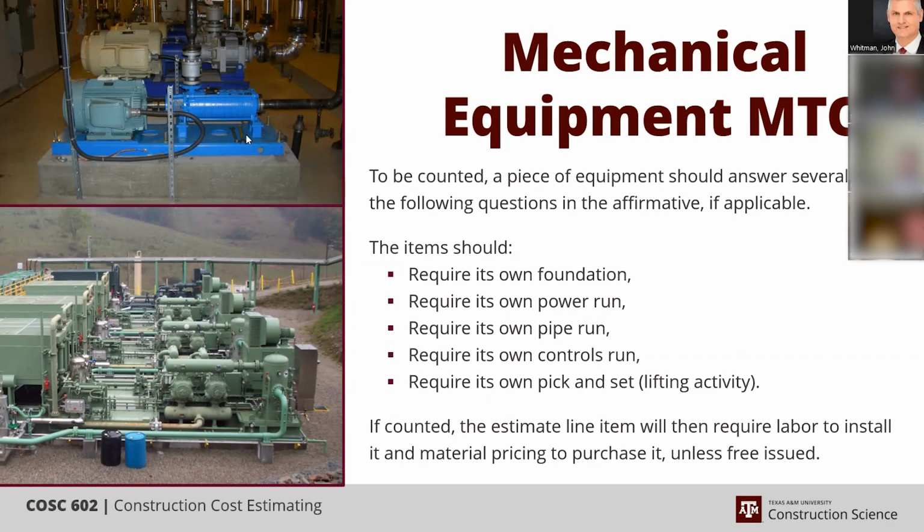Your large pumps, most of your pumps come skidded like this. Pulp and paper plants, typically the motor will come separate. But pulp and paper chemical plants, they normally come pre-assembled, and you just set the whole thing, but you still have to make 3 alignments. This coupling has to be checked 2 to 3 times during the process. But in this case, it has its own foundation, it has its own power, it has its own piping, and then somewhere,